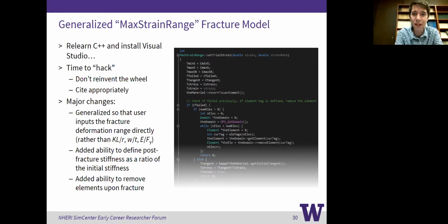But I'm finding that at least in these simple cases where I have a brace to gusset weld fracture simulation, it doesn't really change that much. And in fact, because I'm removing the load path to the brace and providing some supplemental but really low stiffness, convergence is actually a lot easier to achieve after that fracture occurs.